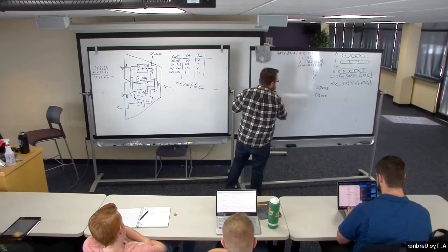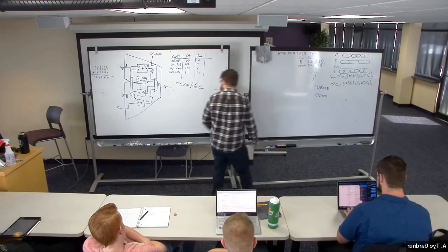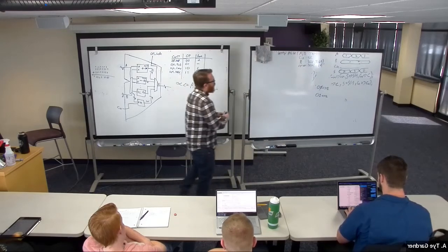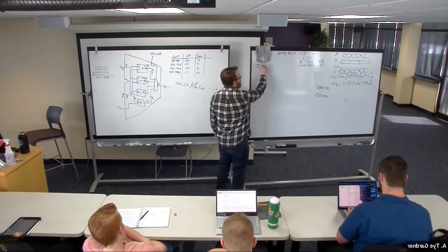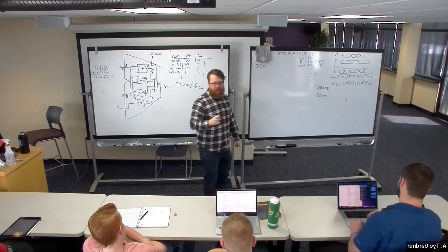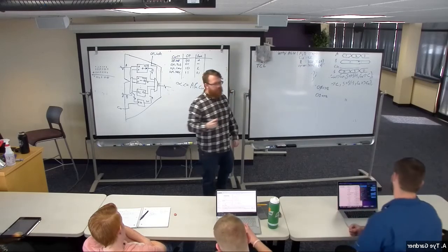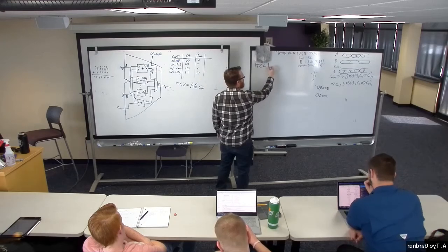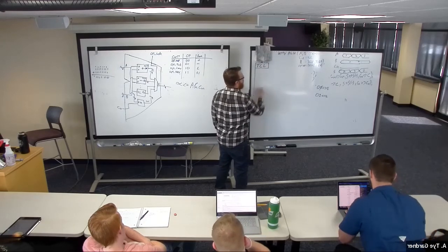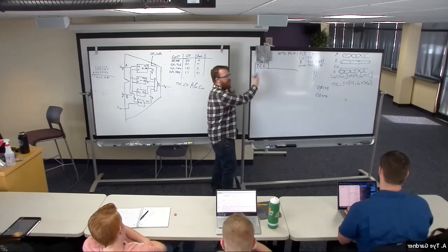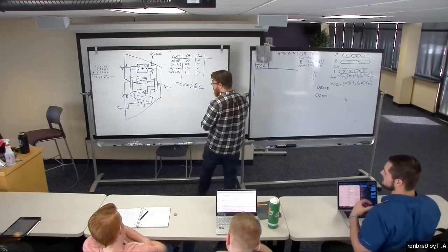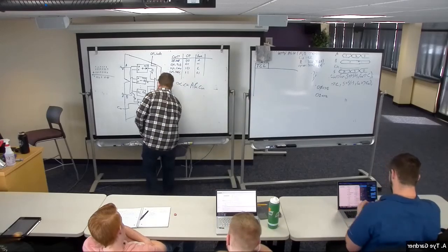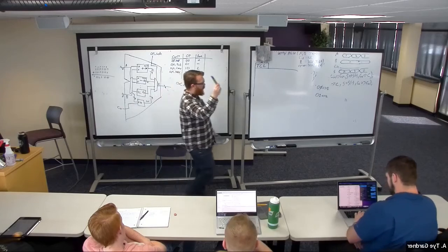When trying to figure out what is wrong with your code, the TCL console, which is near the bottom of Vivado, is your friend. It's going to have a little tab that goes up above it, and when you click on it, it's going to bring up a window with a bunch of code. I wish I had the appropriate colors, because you're going to pretend that this is red.